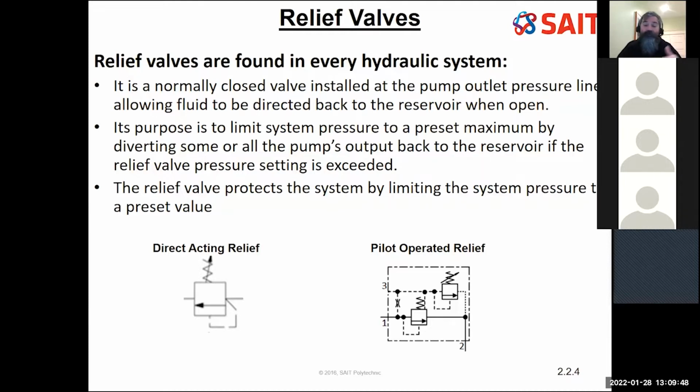The beauty of something like a relief valve is it doesn't fail. It just diverts fluid away from the circuit until the requirement for the high pressure disappears. So it's automatic. It's like having an electronically resettable fuse, which we do have on circuit boards and things like that nowadays. We can get electronically resettable fuses instead of your old-fashioned fuse that just blows and needs replacing, like we saw in the multimeters in our MEC 205 labs. So that's why it's